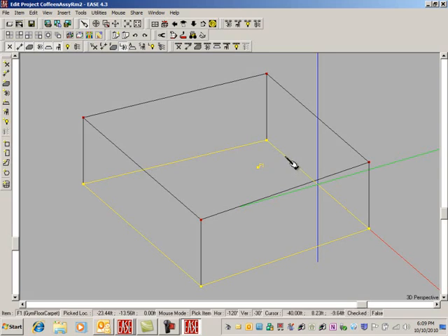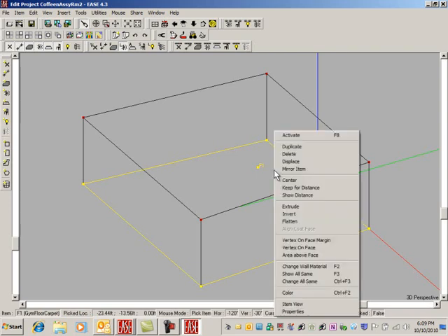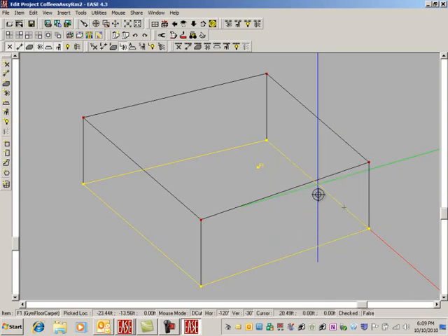And then if I want to move the model, if I do a Control and a left mouse, I get the move hand, and I can get this over centered. I can see it a little better now. That's good. So I think I'll make a face here. And this will be an inside face from here to there, to there, to there, and back to here. Create that face. And we could make it chipboard or wood or whatever. We can just leave it chipboard. Okay, there it is. And now we also have a stage floor.